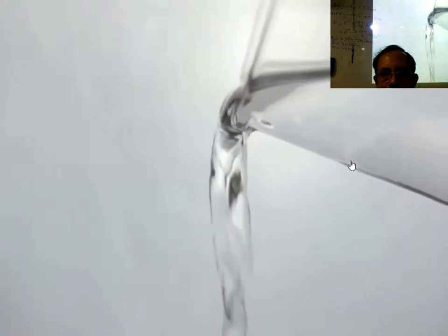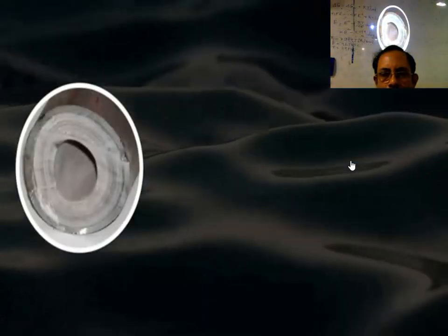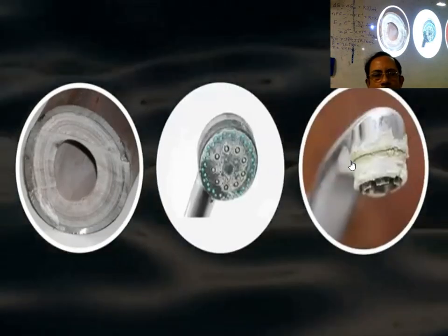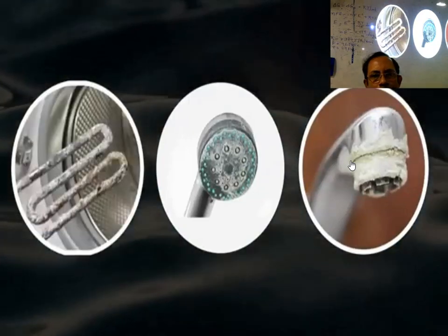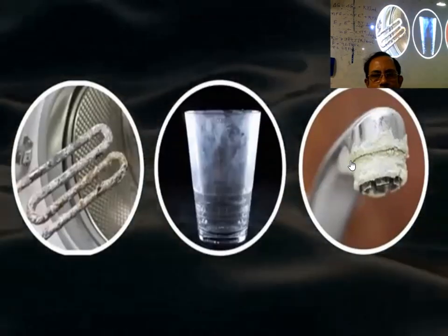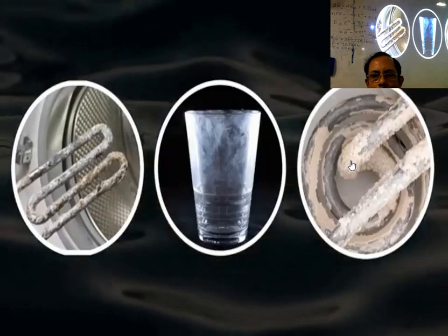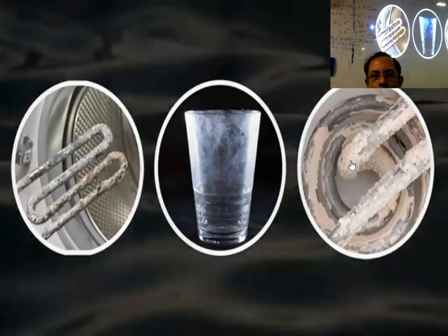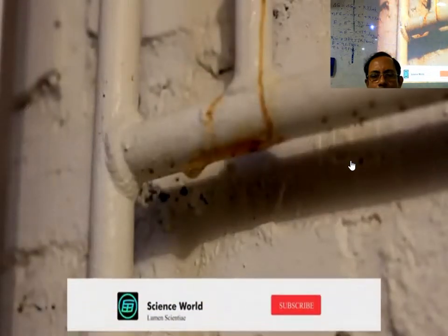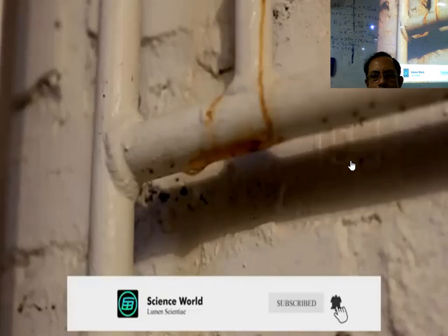Hard water is generally not a health risk, but it is a nuisance. When hard water is heated, a certain amount of water evaporates, causing the minerals suspended in it to precipitate. These residues can then accumulate inside pipes, water heaters, washing machines, and dishwashers. The result is reduced water flow or blockages, stress on pipes and fixtures, spots on glasses and dishes cleaned in a dishwasher, and less effective clothes washing due to a lack of soaps.